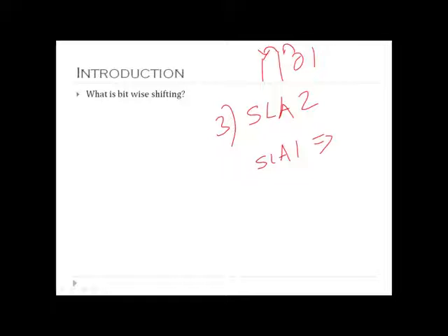So same number we consider 1101. Now the third type is shift left arithmetic twice. Now first I'll perform shift left arithmetic once. So I'm shifting on left, right? So here this will come here, this will come here, and this will come here. So my number would be 1, 0, 1. Now this place has become vacant, but I won't append 0. What I'll do is keep this one as it is, right? So the same one is copied here, and also it is retained there.